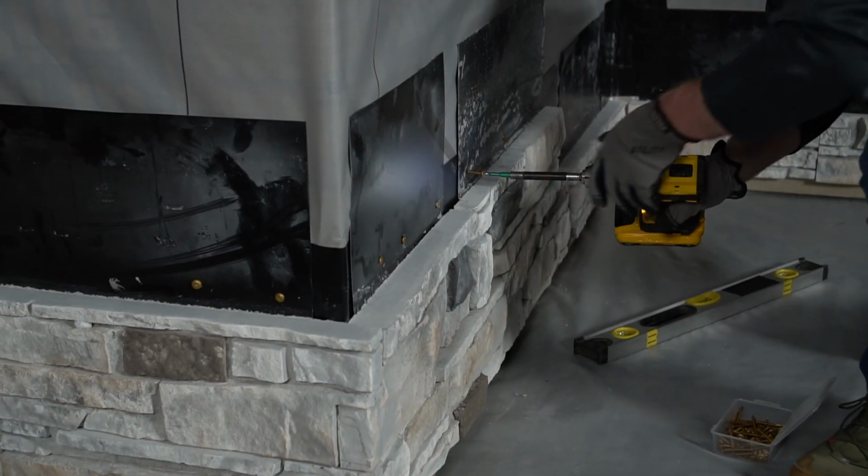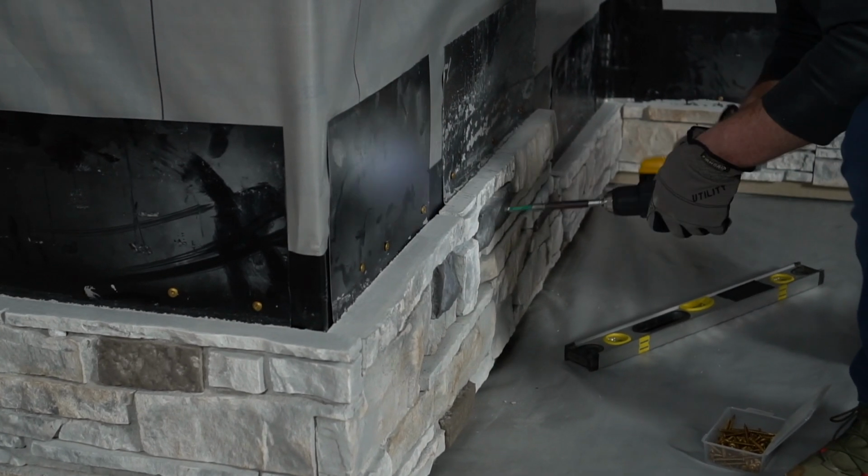Never install a corner or panel unless there is a stone or transition below it. In the case of trim, the trim will set the edge. Step flash the edge as you install the flat panels.